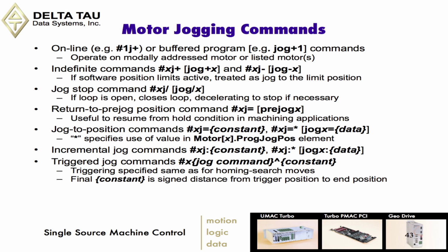Incremental jog commands, J:constant and J:*. So that will cause me to incrementally jog that number of counts. And the same thing with the ProgJogPos element. If I was to do J:*, it'll cause me to incrementally jog by the amount in that element.